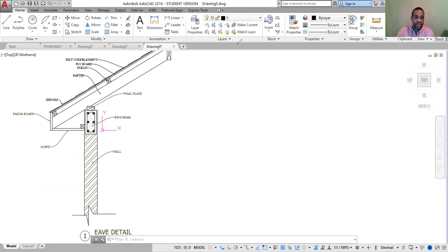For a shingle roof, for this section, we would have plyboard or timber. Another layer that we would have on a shingle roof is underlay. And underlay is a black tar-like mat that acts as a waterproof barrier between the board and the shingle. So you nail the shingle onto the underlay through to the board.